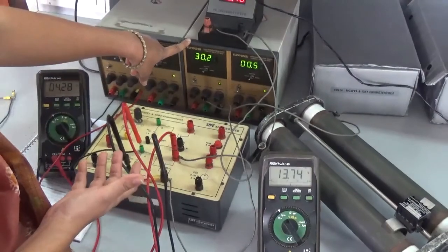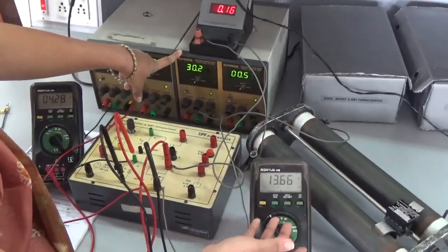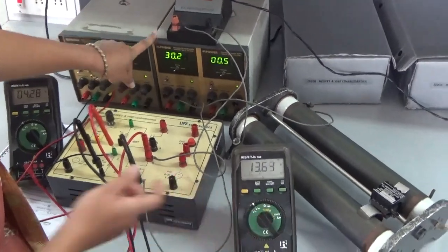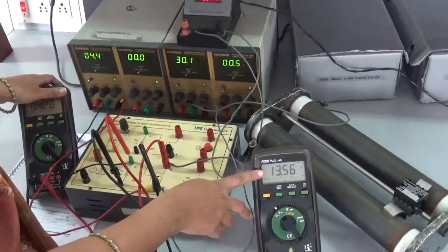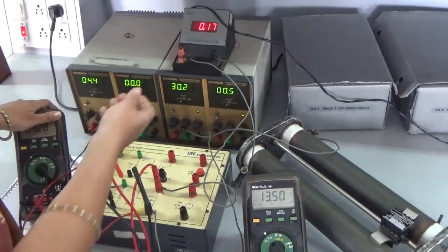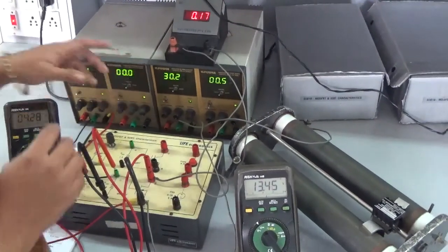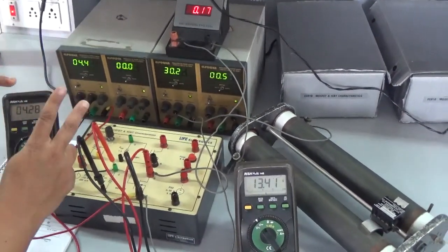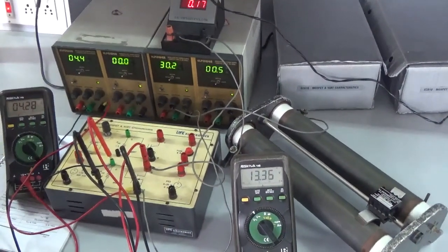For output characteristics, instead of setting it to 50%, you set it to 60 or 75% of the voltage. That means set VDD to 30, vary VGS until the voltage across the MOSFET reduces to 20, then reduce VDD to 0, again increase it and take the output characteristics. Like this you need to take two sets of readings for transfer characteristics as well as for output characteristics,